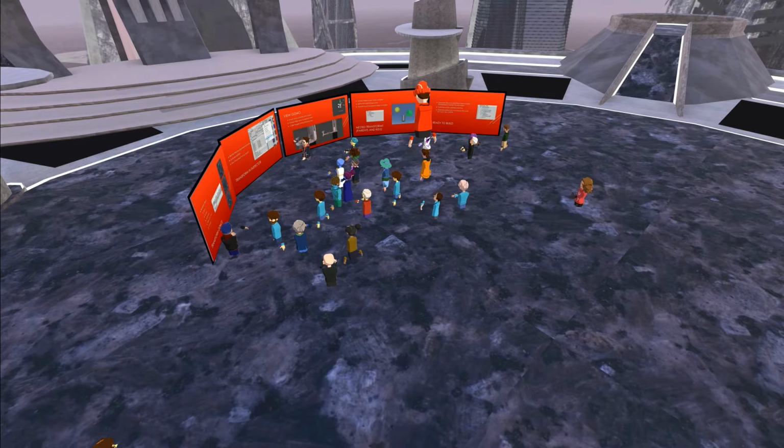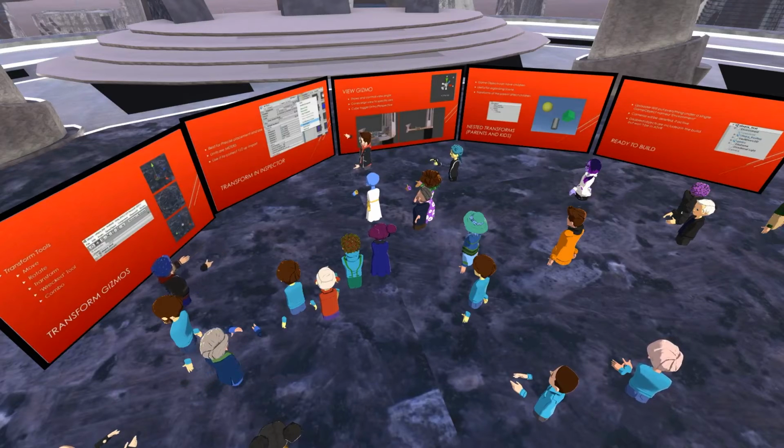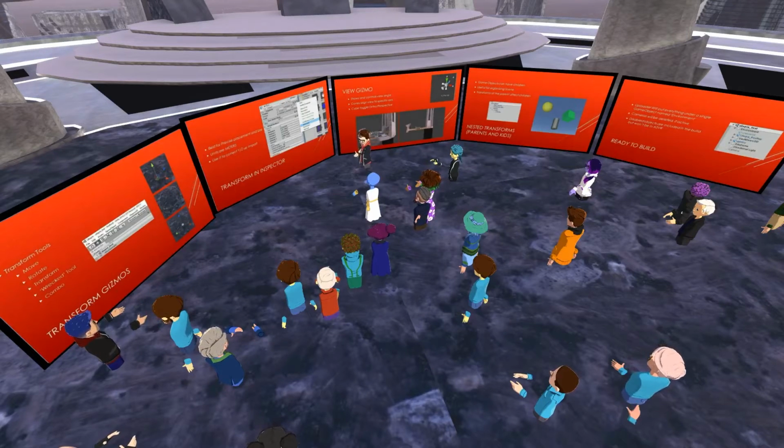Another thing that I do to quickly move things or make sure that things are quickly aligned with view, if I click on that little gear symbol up in the corner, I'll get a bunch of options, 2 of which are reset position and reset rotation. I can also reset scale. If I do the reset up at the top, it's going to do all 3 of these, and that may not be what I want. But reset position is always going to move it to the origin. Reset rotation is always going to align it with whatever its parent is.